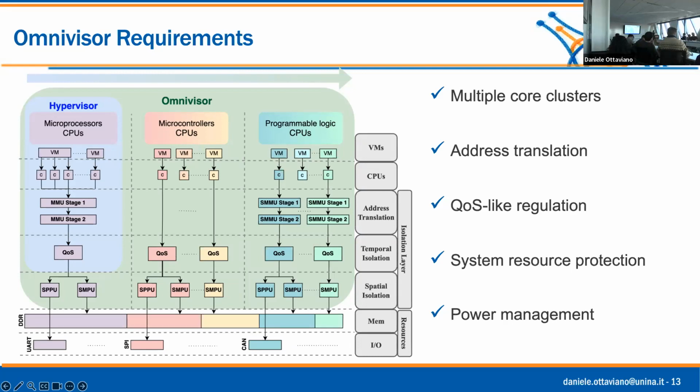So, curious. Well, it depends what you're trying to do. If you run an SMP system, and one of the devices is the DMA synthesized on the FPGA, and you're now launching a VM that is using the DMA in the FPGA, ideally you want both of them to look at the same IPAs, right? So you set up the SMMU so that the DMA sees the same intermediate physical addresses of your VM. That's what the SMMU is for.